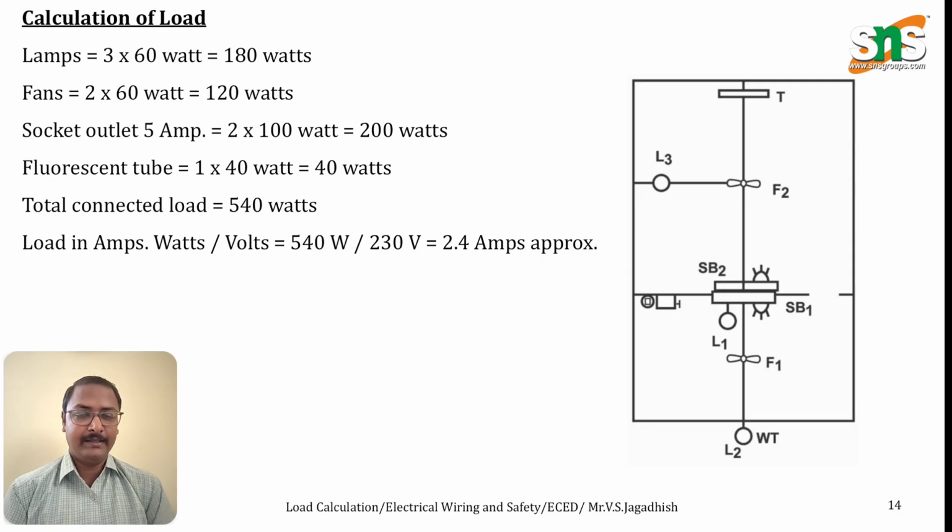So this is how we draw a simple line diagram. According to the requirement of lighting and ventilation, we calculate the number of appliances we need to meet those requirements, how these are to be connected by wiring, what load capacity has to be taken from the main line, and what gauge of wire has to be selected in order to connect all these appliances together.